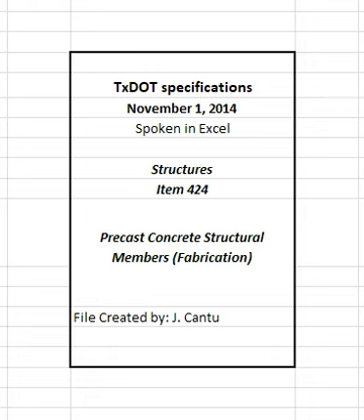Do not allow the stress in the strand to exceed 80% of the specified ultimate tensile strength of the strand at any time. Do not use any portion of the strand that has been previously gripped with chucks in the length of strand to be tensioned, except where gripped with chucks during initial tensioning. Do not drive over prestressing strand. Strand chucks designed with spring caps must be used with the spring caps. Visually inspect strand chucks that are not equipped with spring caps to ensure all wedges are evenly seated after applying initial load. Correct unevenly seated wedges by releasing the stress, repositioning wedges, and reapplying the initial load.